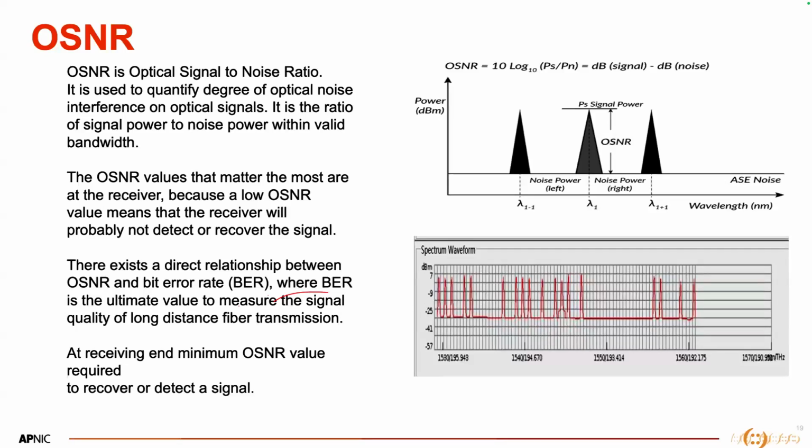Because whenever you are sending the multiplexed signal from one node to another, in the path there will be a distance of 40 kilometers, 80, 100, 120 kilometers. And after passing 120 kilometers of fiber, when the signal reaches the next station, it becomes really, really weak. So it needs to be amplified first. For amplification, we have two concepts.